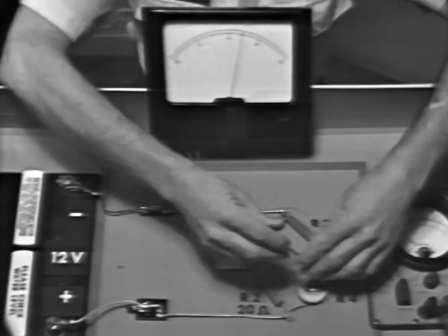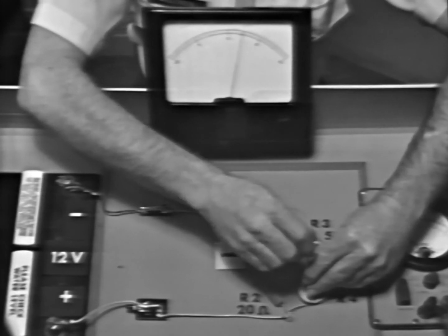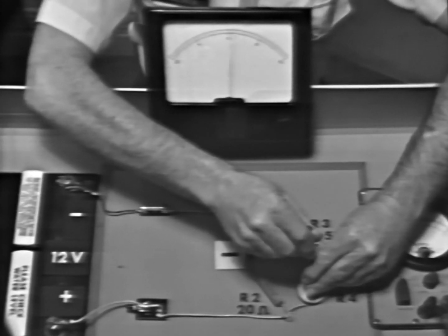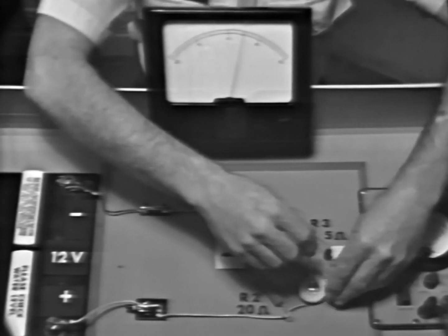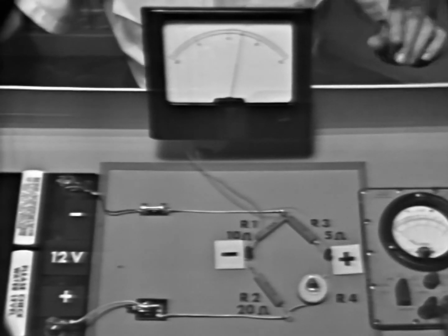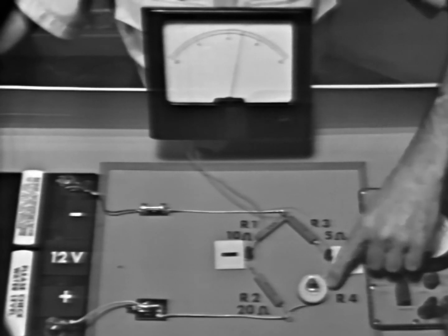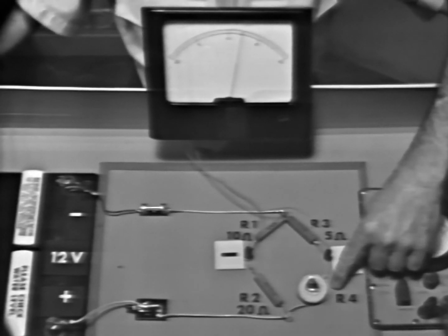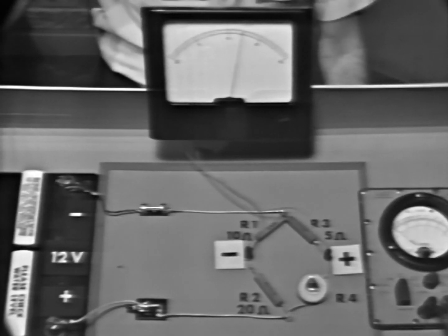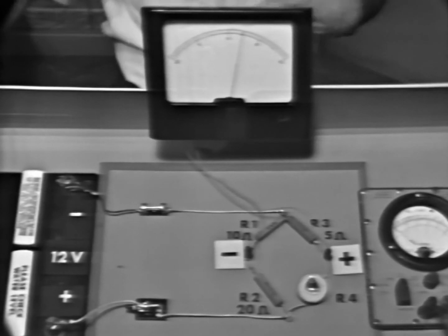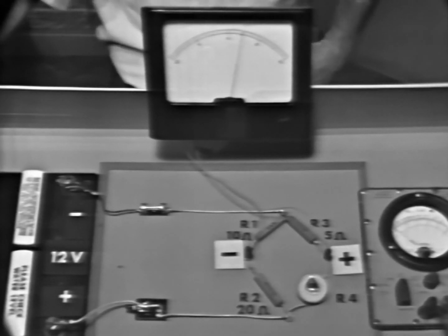So notice then that with a single control, this rheostat, we can cause current to flow in either direction across the bridge. And of course, we can vary the amount simply by upsetting the ratios more. Now, this feature of the bridge circuit makes it extremely valuable in applications such as weapons control systems, antenna positioning, measuring devices, and systems where a highly sensitive control circuit is required.